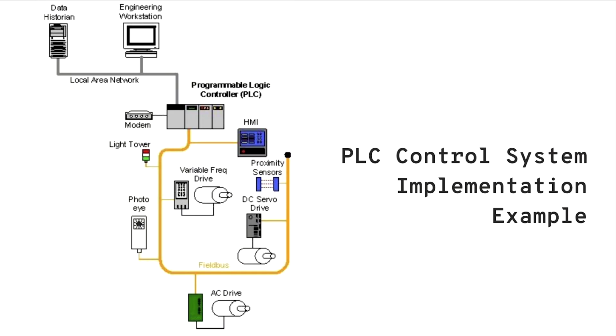In this slide, I have another control system implementation. Actually, we saw that in a part of the DCS system, but here you have a PLC controlling everything, right? There's an industrial protocol here, field bus, and you have your sensors and your actuators connected to it, and also the HMI can be connected directly on the field bus and the PLC, so you can get information about what's happening in that control system, right? But again, a PLC control system implementation is more suitable for smaller control systems.